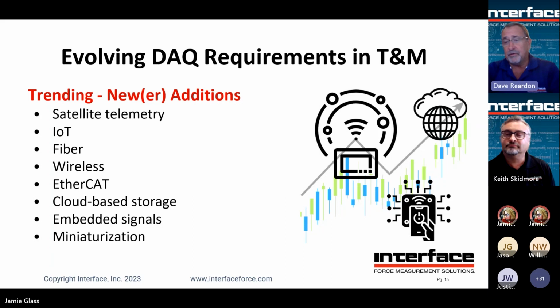In addition, there are some devices in the last few years that have come out that are inductively powering the sensors, such as our axial TQ torque device. It makes it so that for very fast churning measurements, such as you see on motors or helicopter rotor blades or something similar to that, you can attach one of these devices and not have any cabling between the part that is rotating and the solid structure that is attached.